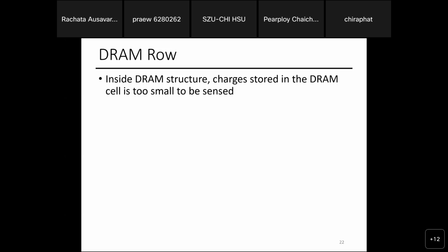If you are asking, why do we just store numbers in binary? Why don't we store them in one single capacitor? Why can't we store 00, 01, 10, and 11, and between 0 volts and 1.5 volts have 4 different regions? It just turned out too hard to do that. We have a really hard time figuring out whether the voltage is at the top part or bottom part. That's why we do binary. Okay.